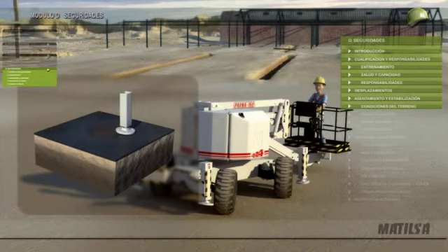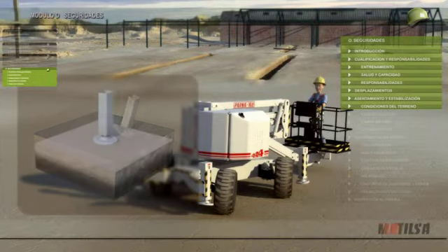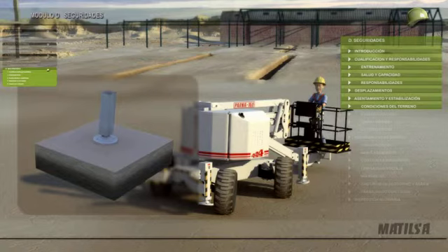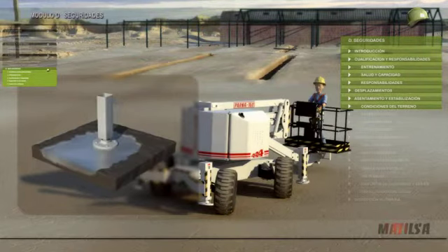Beware of sewage and waste pipes or other obstacles, since the weight of the machine may cause a lack of stabilization. Adverse weather conditions, such as rain, may cause the ground to be completely unstable. In this case, we should not work, even with the use of the stabilizers, since according to the type of the ground, this will allow the stabilizers to sink into the ground, thus causing a lack of stabilization. Frozen ground may look firm, but may break or defrost on the supporting points.